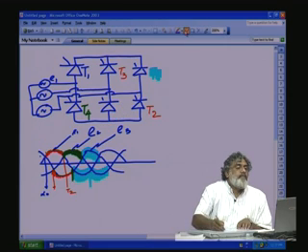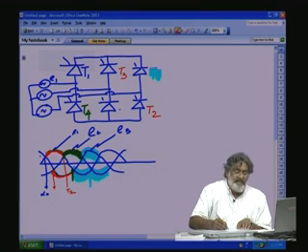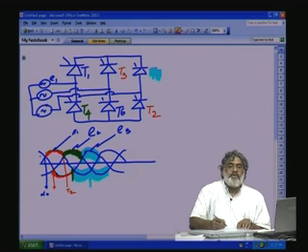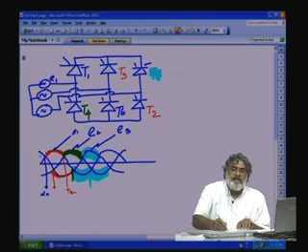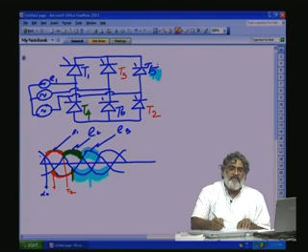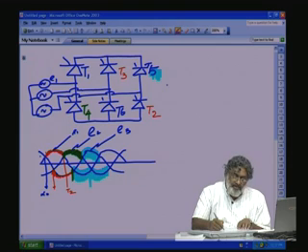So, the next part will be T6, here it is, T6. The sequence, if you see, is T1, T3, then T5, this is T5. T1, T3, T5, T4, T6, T2. This is the sequence with which we have to turn on the devices. Alpha is equal to 0.